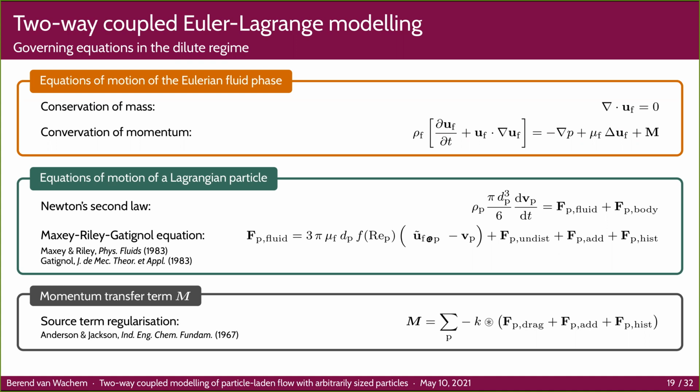So in principle, we could use or expand the framework that we're working on for liquid solid fluidization as well. And in fact, I would say that the impact is much larger because the particle Reynolds number in a liquid solid fluidized bed is typically much lower because the slip velocity is smaller. So the short answer is the framework can be applied. It's not something that we have looked at yet.